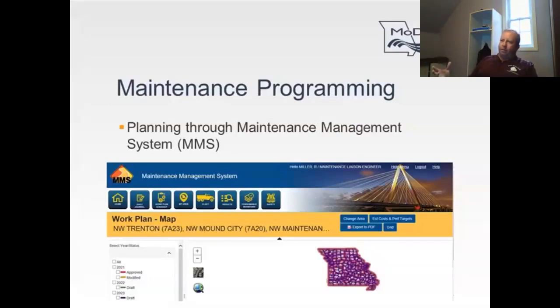This is a preventive maintenance effort, typically done every 5 to 7 years with bridges. So it's a very important effort that we have to preserve some very expensive assets on our system, these bridges. But let's say you have a situation where every year we purchase the sealing material and we apply that sealant ourselves.